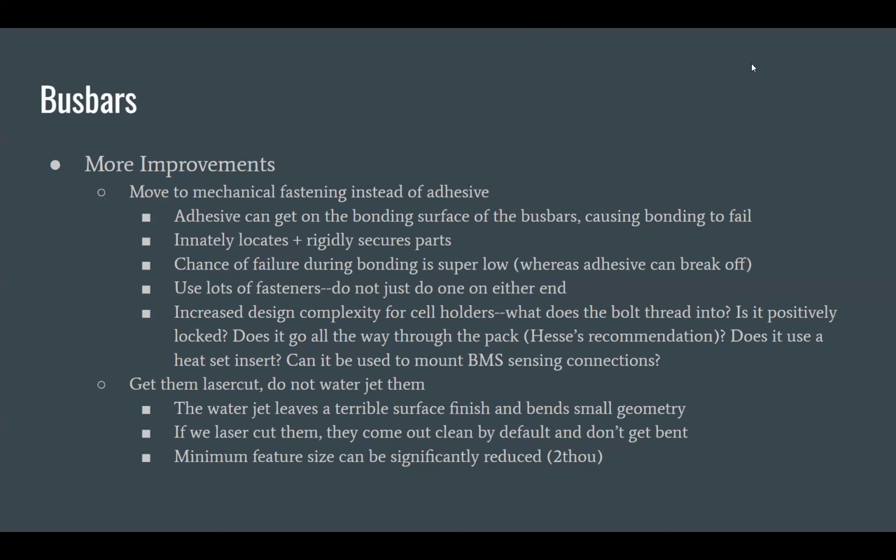They said they've had big problems with it. Particularly, because a heat set insert specifically melts the plastic, they get a lot of doming on the side, which means that when you bolt the bus bar on, the bus bar doesn't sit flush to the surface. It sits a little bit above it, and then you get the exact same problem as with our advanced bus bars, where it'll just wobble in the middle when they try to mount it. Obviously, if we could make a way that guarantees that is not a problem, then that might be okay. But Hess definitely said this is something we've had historical issues with in the past with any form of heat set inserting, and they generally recommend not to do it.